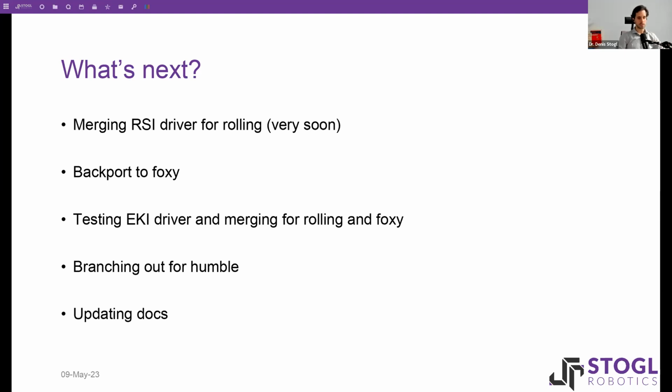And finally, we have to revisit and update some docs. What is important, I just realized that I missed this here. Together with our client, we also extended the ROS-I setup for newer KSS versions, so version 8.6 and above, because the ROS-I setup on the robot was changed. So there are additional KRL files. There is a pull request with that. Since CI was failing, I didn't merge it yet.